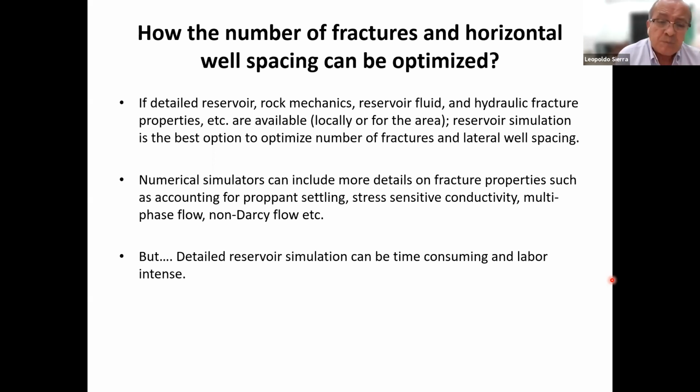So using the reservoir simulators, we're going to be able to include, for example, the stress effect on the proppant, the stress effect on the rock, or the permeability or porosity. We can consider multi-phase flow or non-Darcy flow, etc. Depending on what information we have, we can try to use that in the reservoir simulation.